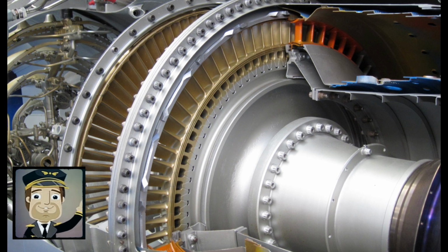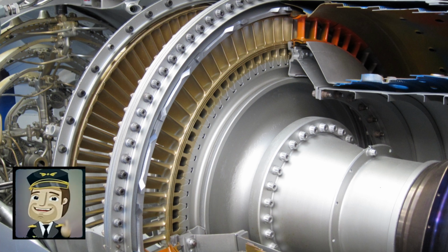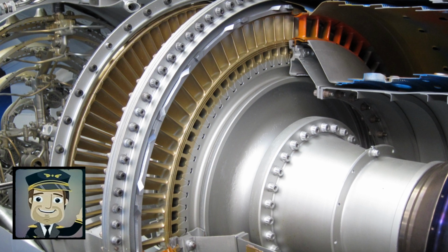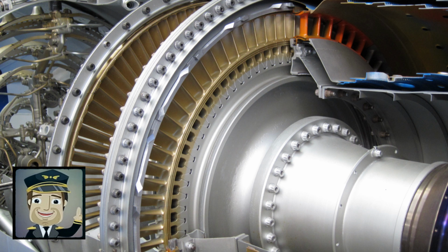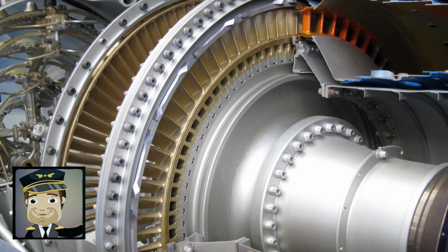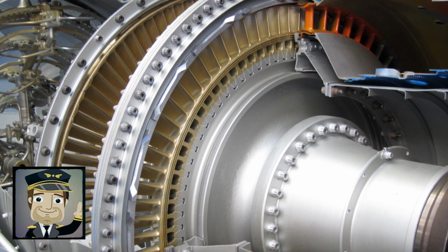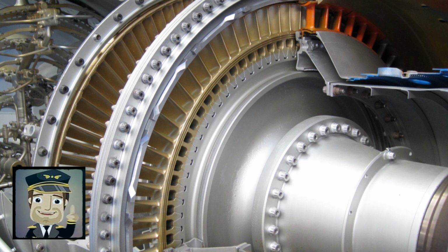It was followed by the aft fan General Electric CF700 engine with a 2.0 bypass ratio. This was derived from the General Electric J85 turbojet that powered the larger Rockwell Sabreliner 80 model aircraft, as well as the Dassault Falcon 20, with about a 50% increase in thrust to 4,200 lbf.